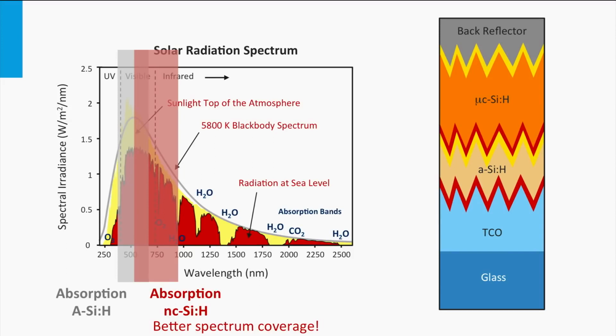First, the amorphous junction has the highest band gap of both materials and will act as top cell. The top cell is the PIN junction that is facing the front and where the incident light passes first. The cell with the highest band gap acts as the top cell, as the spectral part with the most energetic photons has the smallest penetration depth in materials. The bottom cell is the cell with the lowest band gap. This cell has to harvest the photons from spectral parts with the lower energetic photons.